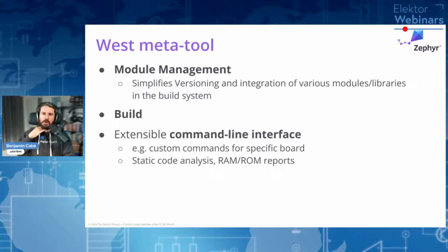It's effectively the tool that helps you provision your environment, and keep all your dependencies up to date: the Zephyr code base itself, plus all the third-party libraries you might be using, like Mbed TLS if you're doing network communications and HTTPS. It also helps you with building and setting up compiling your code, potentially testing it, and it has lots of interesting command line options that I will try to demo.